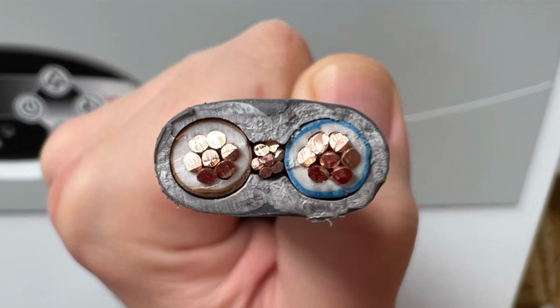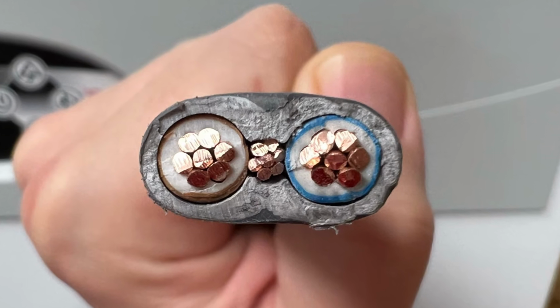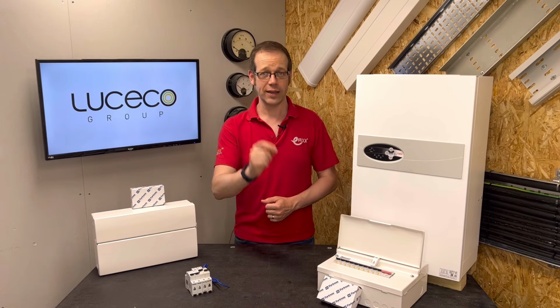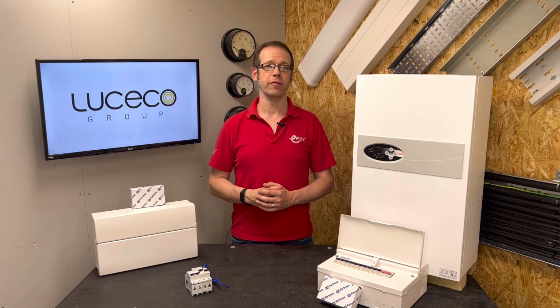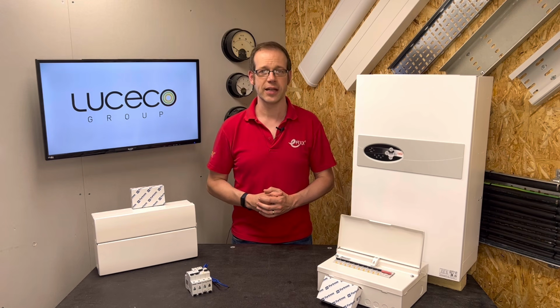So there we go. That's why the CPC in the cable is so much smaller than the line and neutral, and how we confirm that the CPC we're using will in fact be big enough to cope with the fault current flowing through it. In other words, we've confirmed the thermal constraints for the protective conductor.